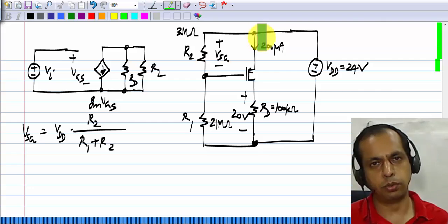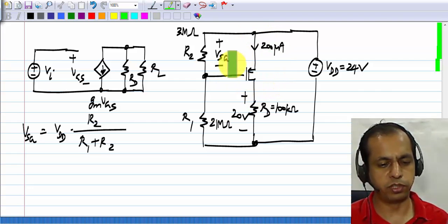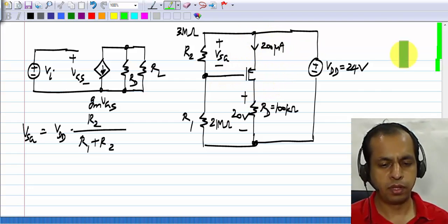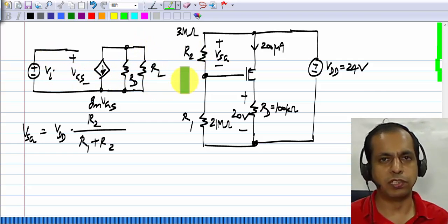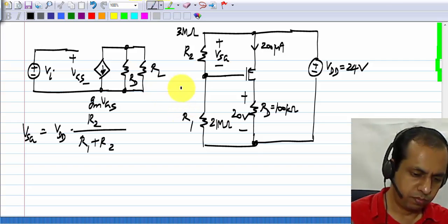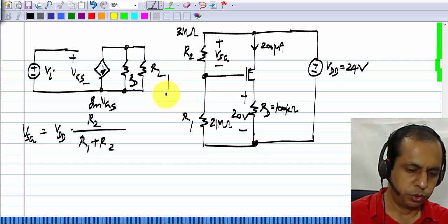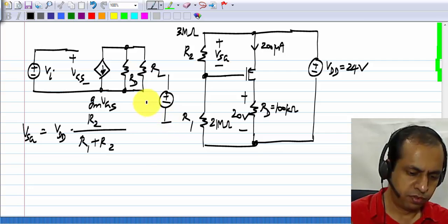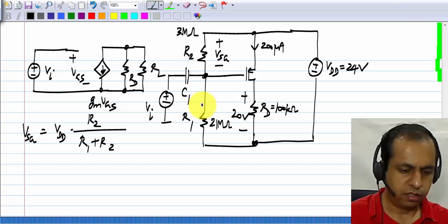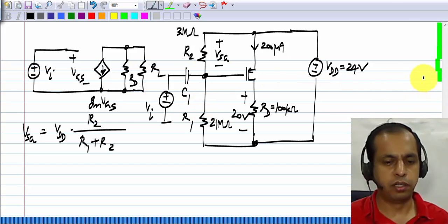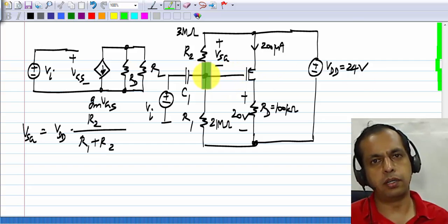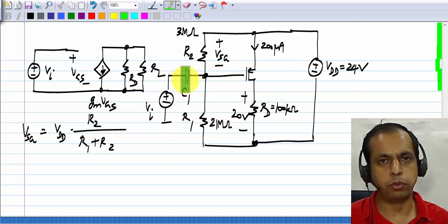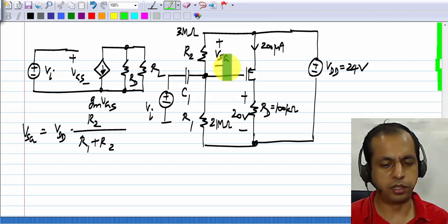We have a source drain voltage of 4 volts and a source gate voltage of 3 volts. And we have to add the input voltage and also connect the load resistance. How do we add the input? It's the usual AC coupling stuff. We have VI and connect a capacitor C1 to couple it, so that if you choose C1 to be sufficiently large, at this point you will get the quiescent gate voltage plus the input voltage. The input voltage will get added to it. Okay.